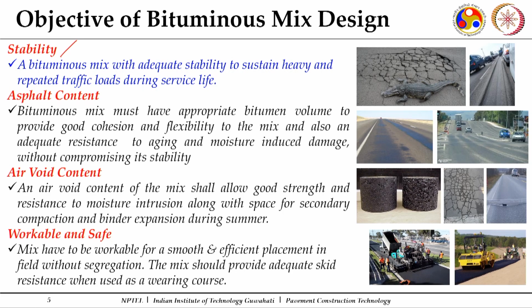Good stable mix means when traffic comes over it, it should not show these deformations, or it should not show these kinds of cracks. These cracks very much resemble the skin of an alligator. So, you can see an alligator is there and these cracks are there. You can see there is some flushing, the binder has come up on the surface. You can again see some amount of depression and flushing, again the cracks are there, some amount of depression is there. This is construction of a bituminous mix going on.